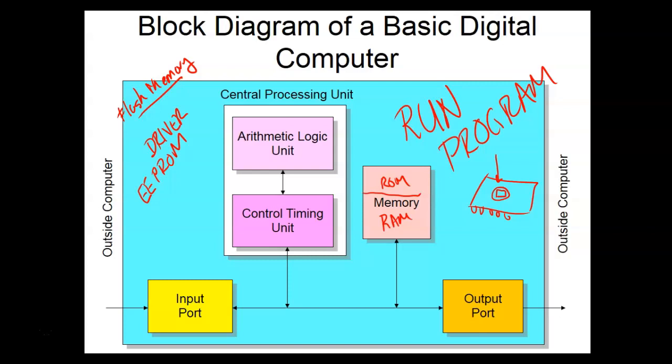When I hooked up one of the PLCs to this computer, which is running TIA Portal version 15, the first thing it told me is that I needed to upgrade the firmware in my PLC. So I have to be careful on this one, because most of y'all are running version 14.